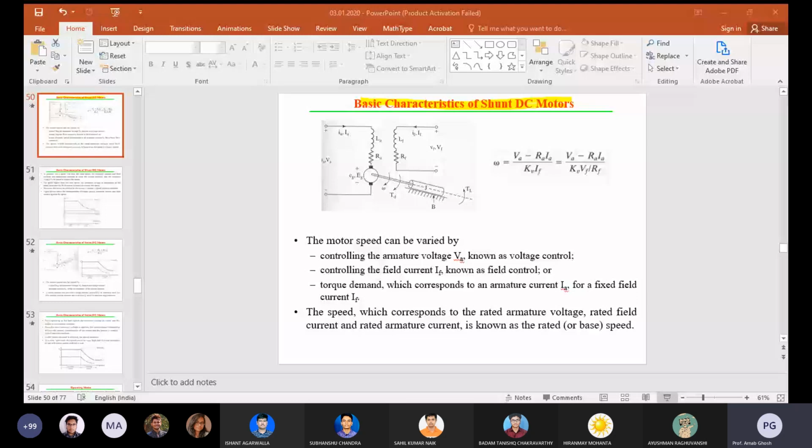With the motor still running in the same direction, the armature current is reversed, thereby producing a braking torque. For the series motor, either the armature terminals or the field terminals should be reversed, but not both. These are all very important features of plugging.